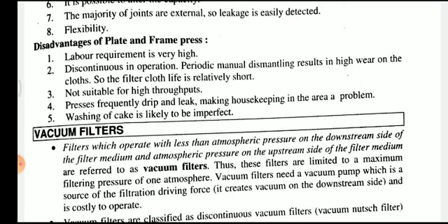The press frequently drips and leaks, making housekeeping in the area a problem. Washing of the cake is likely to be imperfect. So these are the disadvantages of the plate and frame filter press.